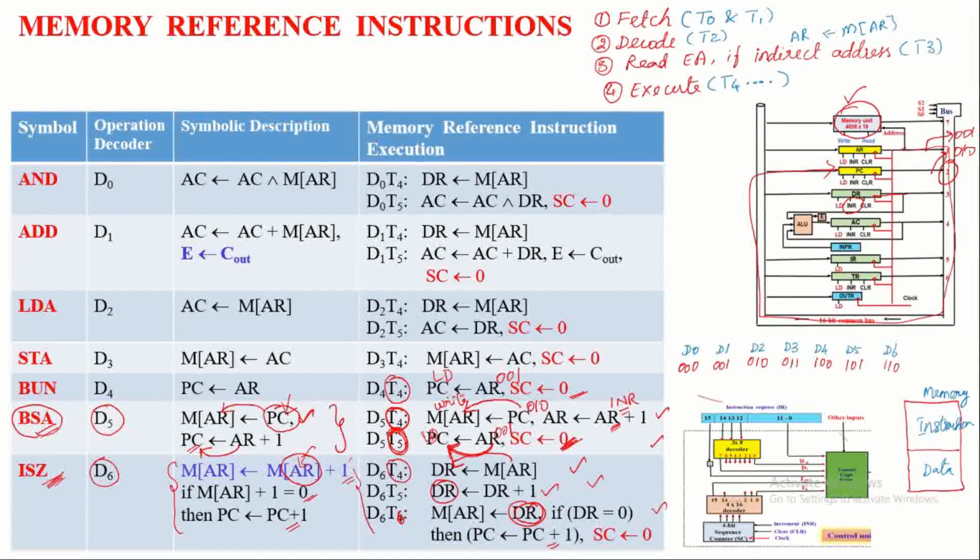Here the incremented content will become 0 only when negative values are stored in the memory unit. Usually, negative numbers are stored in memory in 2's complement form. Whenever those negative numbers are repeatedly incremented, the value can become 0.